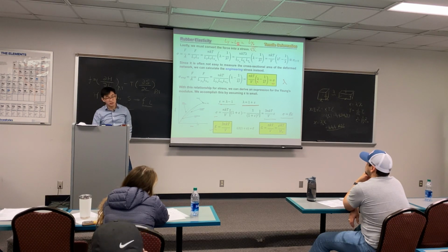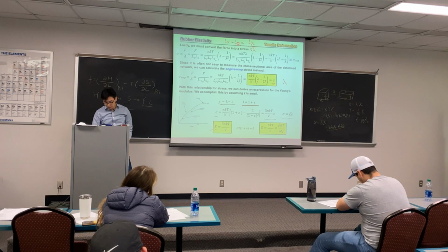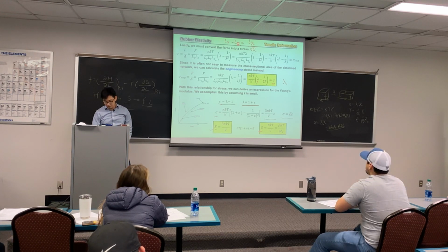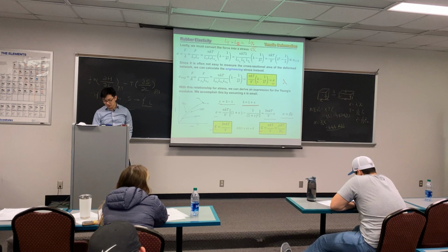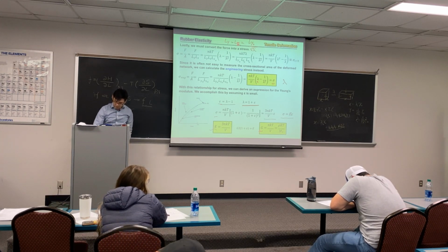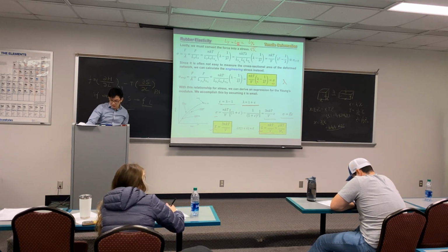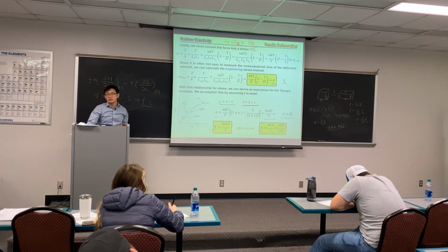the shear modulus. When the Poisson ratio is 0.5, the shear modulus will be 1/3 of the engineering modulus or Young's modulus. It will be directly equal to nkT divided by V. Okay? Is that simple? kT is constant, so your modulus is literally proportional to the number of strands per volume.